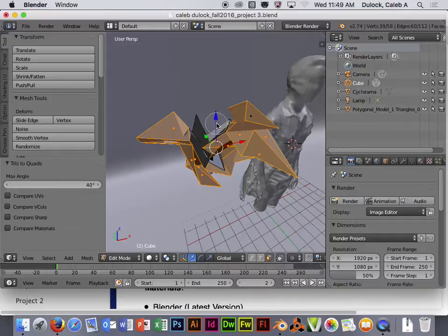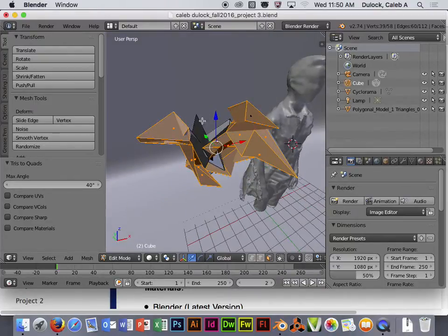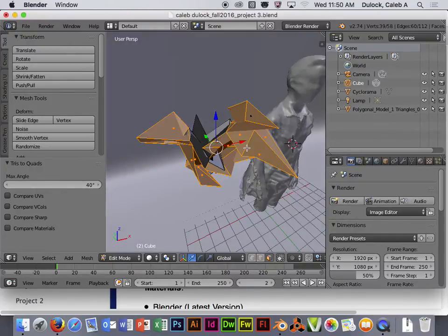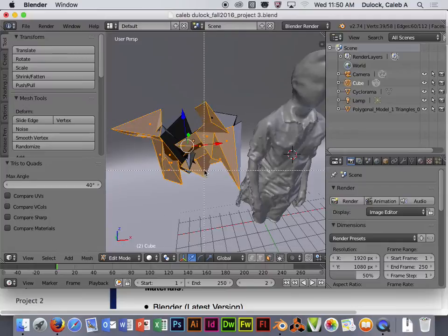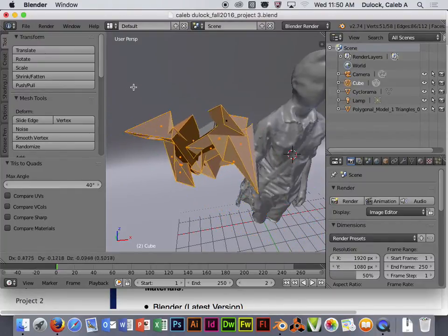Now, again, with this tool, if you want to deactivate it, you have to in order to do anything else in Blender. So you can hit Escape after you're done selecting, and it'll disengage the tool. And then you can do whatever adjustments to the model you need to after that. And that's how you can work with selections. Border select is a little bit different. If you use border select, it'll actually allow you to click and draw like a little selection screen area, rectangular window, and it will grab anything that falls inside of that window based on the viewing angle that you're currently on.